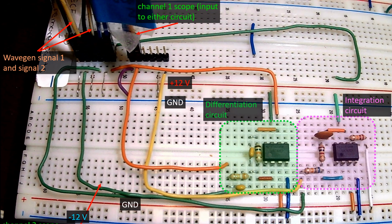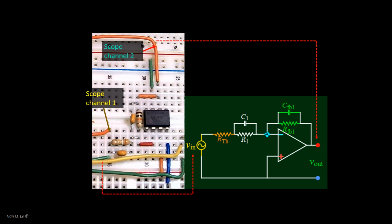Both scope channels are used to monitor the input and output of each circuit. Given only two channels, only one circuit can be measured at a time. The 6-pin connectors have wires connected to both input and output of the circuits, and the scope input cables can be mechanically multiplexed to appropriate pins as needed. This is a detailed illustration of the connection of two oscilloscope channels to the input and output of the differentiator